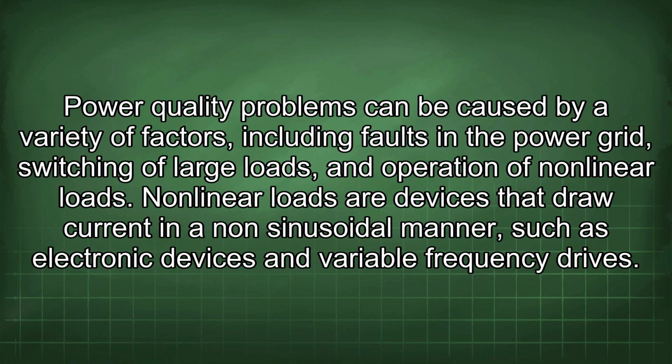Power quality problems can be caused by a variety of factors, including faults in the power grid, switching of large loads, and operation of nonlinear loads. Nonlinear loads are devices that draw current in a non-sinusoidal manner, such as electronic devices and variable frequency drives.